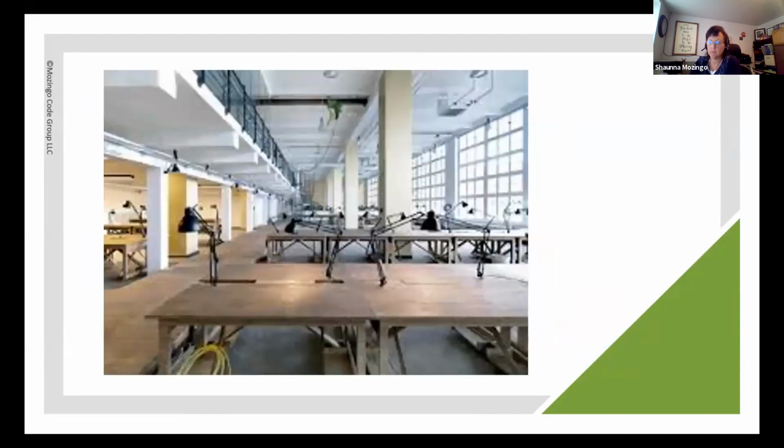Same with open office areas. It'll be interesting how we treat open office areas moving forward. It was a big move to have open office areas. I don't know how the pandemic has affected how we do open office areas anymore. But we just fine-tuned it. So occupancy sensor control function in open office spaces over 300 square feet. Number one, required control zones not greater than 600 square feet that would be separately controlled.